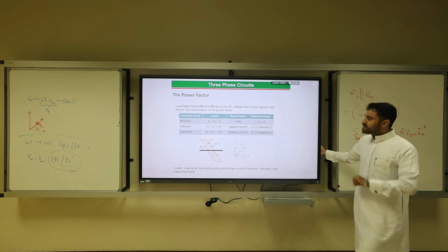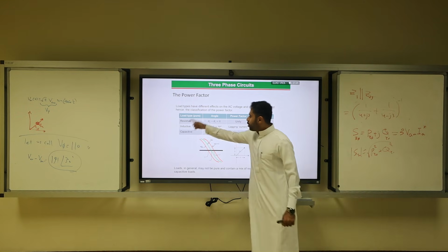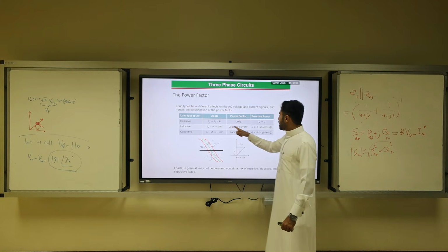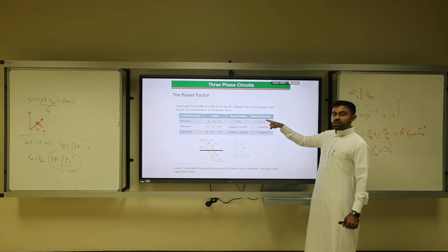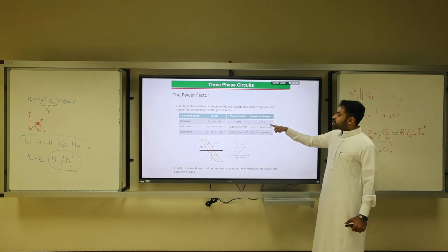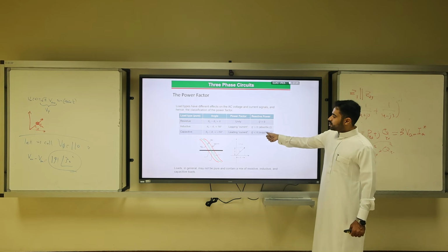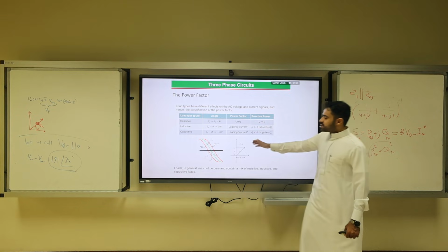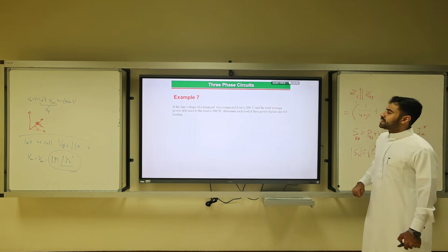So how to calculate this equation? Note that it has to do with the type of load: if it's inductive, lagging; if capacitive, leading. One other thing to know is that Q is 0 for unity power factor. Q is positive for inductive and negative for capacitive. Positive means absorb. And this is how we change them in the curve. That's not important for today's lecture.